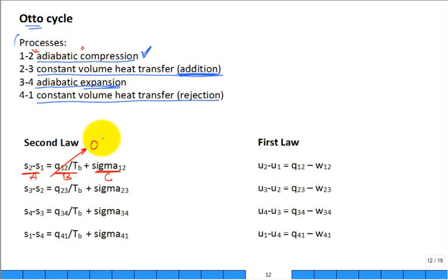Hence that term I said B is 0. Somebody else said it's reversible. There's no entropy generation, sigma 0. What do you conclude about the process 1 to 2? Constant S. Oh, there's a fancy word for that. Is that adiabatic, isochoric, isenthalpic, isentropic, isobaric, whatever? Isentropic. Yeah, it's isentropic. S is equal to a constant.